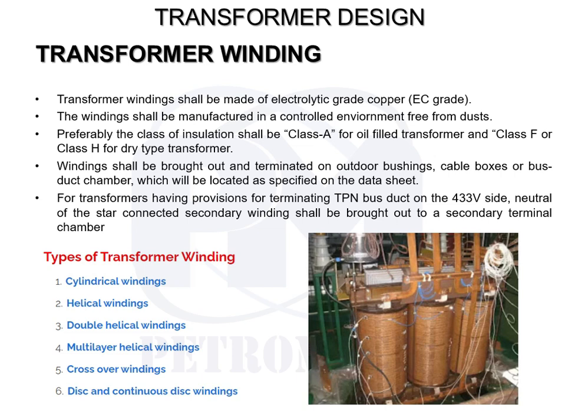The winding has to be manufactured in a controlled environment free from dust. A very, very important point. If there is accumulation of dust or any other foreign particles, that can eventually lead to a dielectric breakdown in the winding. So we have to be very sure about the environment where it is being manufactured.